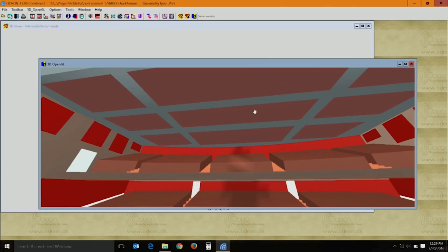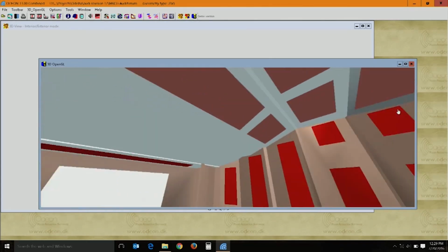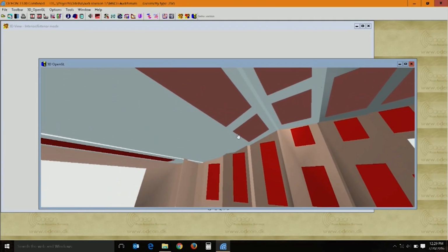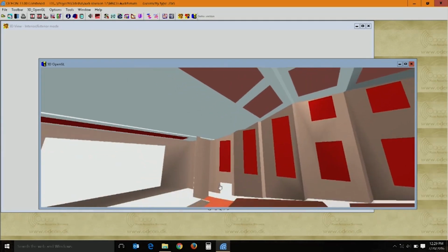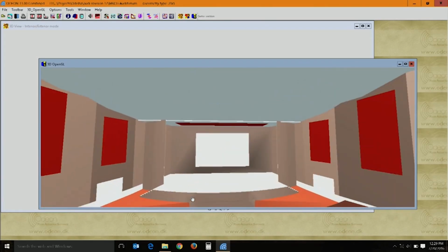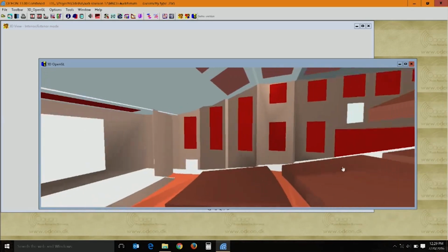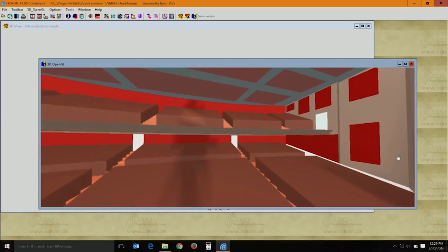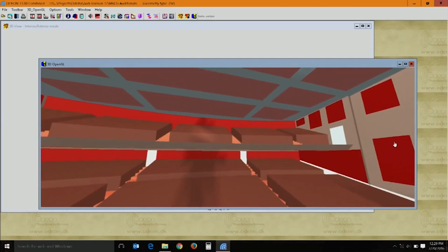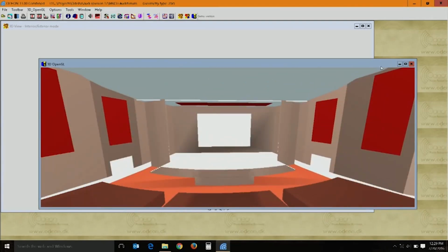There are panels where acoustical absorption is actually provided, plus you also have a certain inclination of the ceiling which was designed specifically for taking into consideration the initial and late reflections, plus there are acoustical reflectors and absorbers provided on the side walls. You have a balcony and below the balcony. We will get into the details one by one.